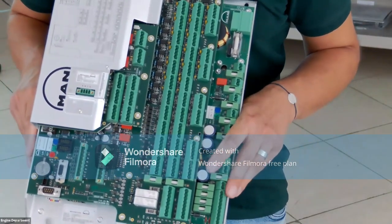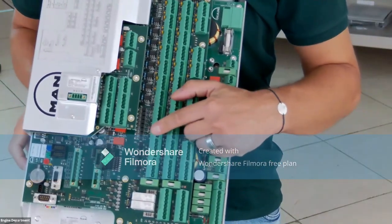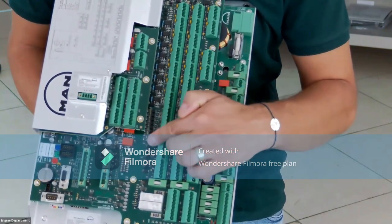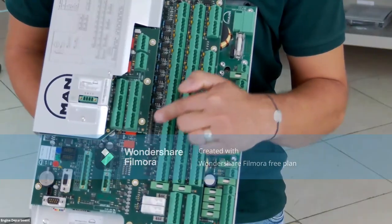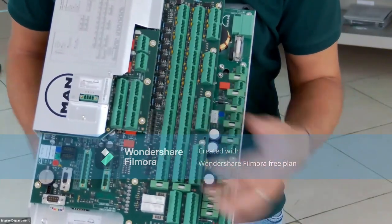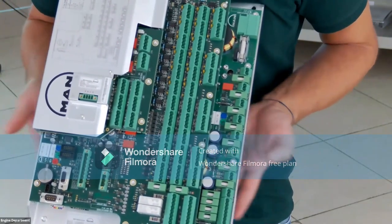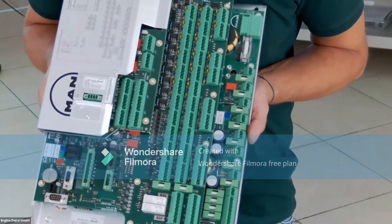ID key have priority. So in this moment, automatically, the ID key, it will ask to the MPC to erase, to delete previous application, which is scavenge control unit, and to install the CCU3 application according with the ID key identification. So it's not required to do any additional job from our side if we are interchange the MPC from our engine. Is it clear?